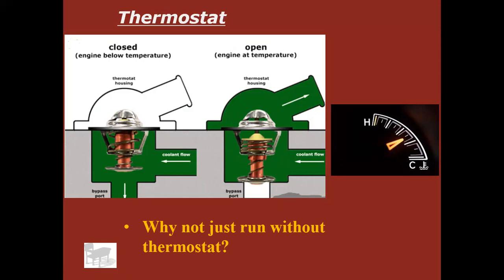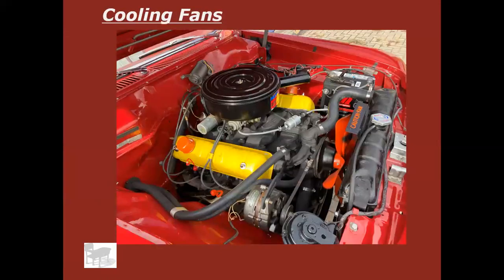I've done this: if you pull a thermostat out and just run the vehicle, your engine's probably going to run, depending on the weather, between 120 and 140 F. You're not going to get very good gas mileage. Gasoline does not atomize very easily in an engine that's that cold. So you're going to lose horsepower, you're going to lose gas mileage, and you're going to cause excessive wear on the engine, which is another story for another day, but not something you want.